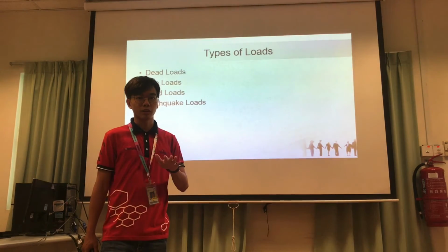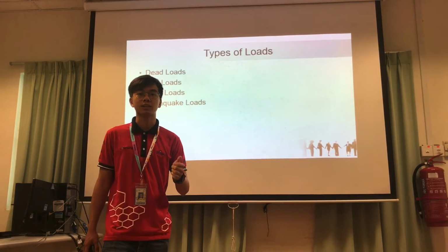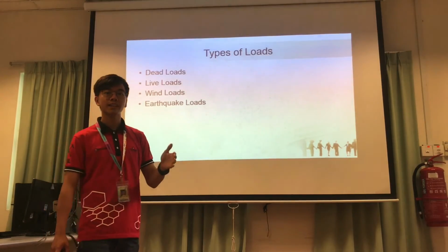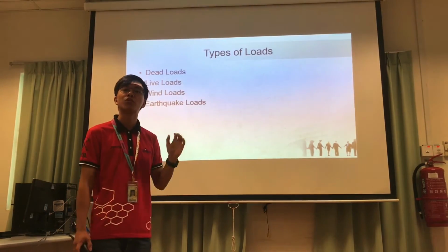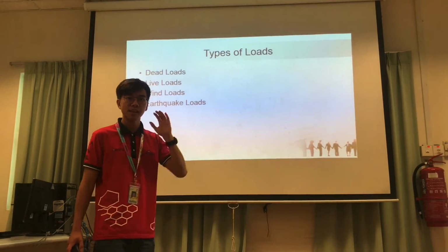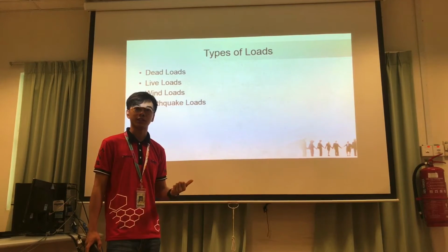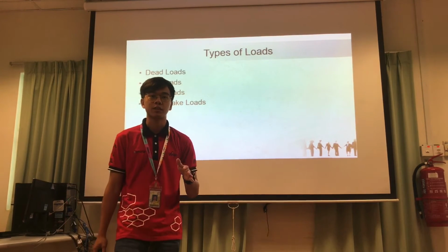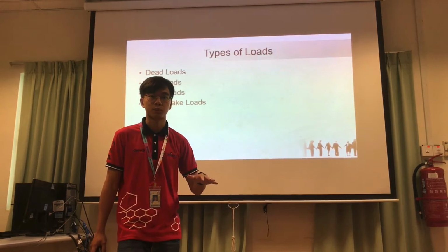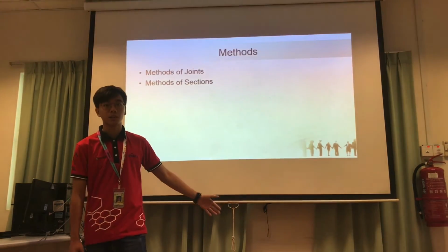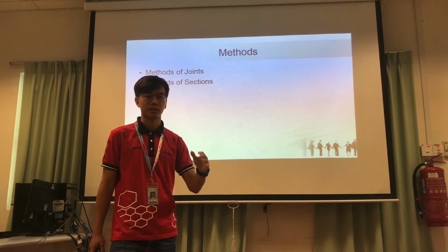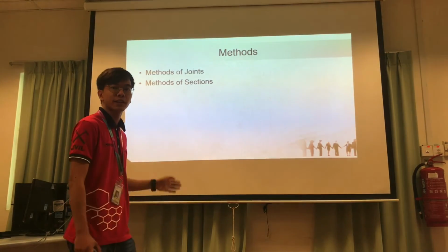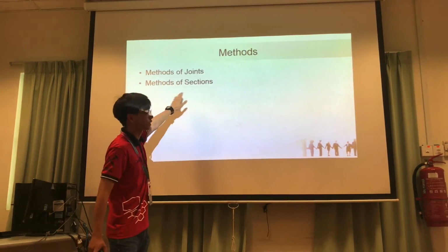Dead loads are composed of the weight of the structure, and the superimposed dead loads that comprise the floor finishes and the weight of the partitions. Next is the live load. The live load consists of movable loads that the structure may carry. Depending on the height of the building, wind load is considered. Lastly, earthquake loads are additionally considered based on the geographical factors of the project. From the model, the internal forces of each element are calculated. The calculation procedures are based on the design codes and standards. Various methods are used, such as method of joints and method of sections.